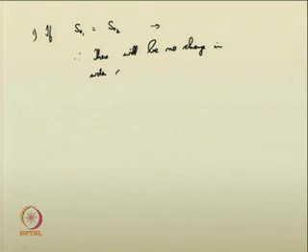If S01 is equal to S02, then of course, normal depths will also be same. So, therefore, there will be no change in water surface profiles.